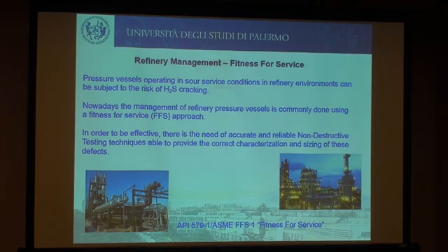So the approach used is fitness for service, and for this reason we need a non-destructive test technique, so we can characterize the defect and know exactly if there is an inclusion inside or a hydrogen-induced cracking.